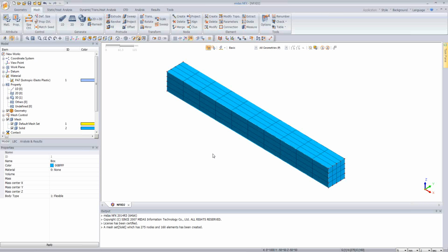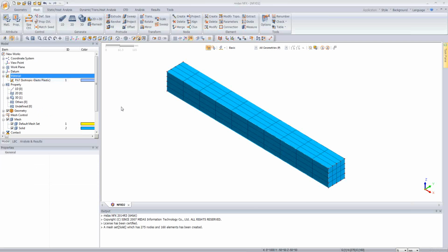handle linear thermal expansion. And basically we will use this methodology, which sounds like that. We will use the thermal expansion feature of the bar element to provide the strain control simulation. So right now I'm going to create the material for the rod element. So once again, I'm clicking on the material.